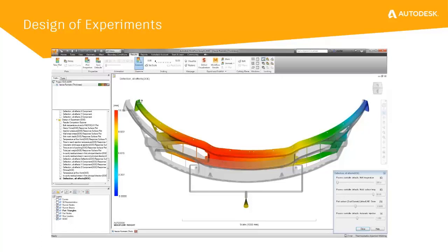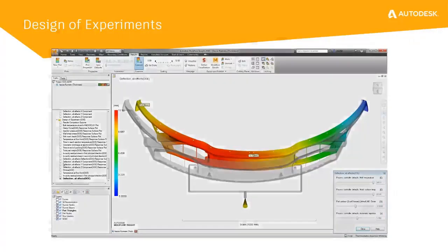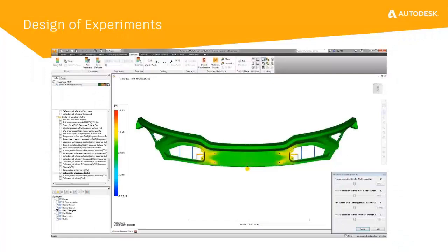This is also important to illustrate the overall warpage trend to determine if changing one variable can actually reverse or impact the warpage trend. These plots can also be created to understand the impact on other results related to part quality. For example, volumetric shrinkage. Again, we can see how changing the mold and melt temperatures impact the volumetric shrinkage, which can be correlated to overall part size and also by locating where sink marks may occur.